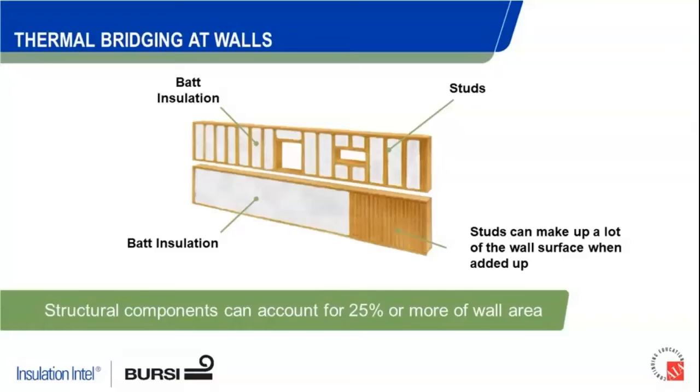So I think the general thought process with insulation is this positive 1 + 1 = 2 relationship. Well, the reality of it is we're not putting insulation in every portion of the wall. Maybe only 75% or even less of that wall even gets insulation within the stud cavity. So continuous insulation aside, I think we can see here that cavity insulation by itself might not be the best solution for creating a good thermal resistance in a wall system.